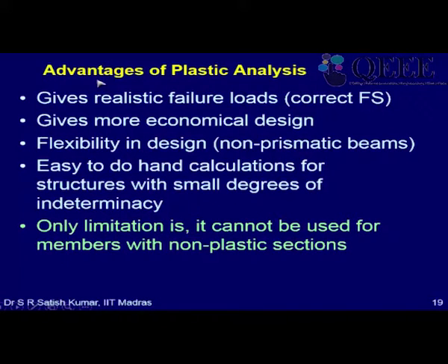We come towards the end of this presentation. Advantages of plastic analysis. Number one, it gives realistic failure loads. As a consequence, it gives the correct factor of safety. The factor of safety which you work out for your working stress type of design using elastic analysis is not really correct, because it assumes that the beam will fail the minute any point reaches yield, which is not true. You may think that it is correct, but it is not. So you get larger factor of safety for indeterminate beams and smaller ones for determinate beams, which we don't want, whereas this will give you consistent factors of safety.